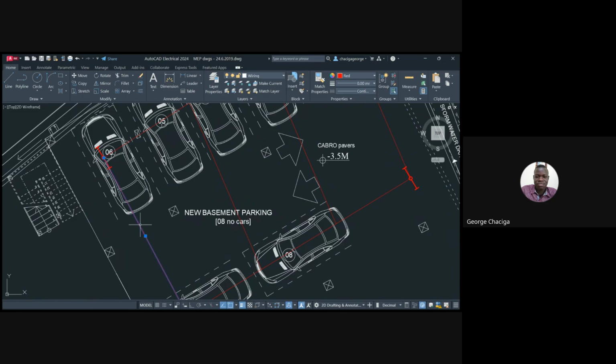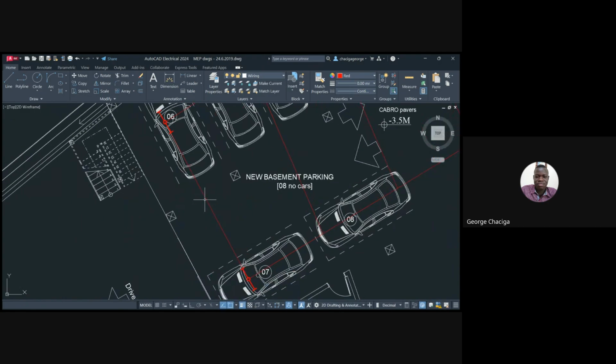Now also for this one, you still select quick properties, you do the same. You come to this length here, you tap in it, you click in it, it brings this calculator. So if you come to that calculator, of course you can see this is already 8.7 meters. You automatically know that I will just need to divide this by 2 to give us our distance that is less than the 4.5, which gives us 2.19. So you don't need to, because this is the line which has a midpoint. So this one, you don't need to use the divide thing again because it has a midpoint.